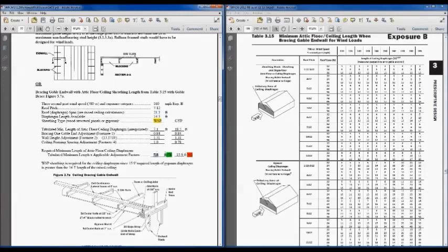That means that you have to sheathe that vaulted ceiling with wood structural panels if you're going to use that to block that end wall on the structure. And then, in addition to that, see this figure here, 3.7a, you're going to have to make sure you've got sufficient blocking into that system to keep a hinge from forming there where you are framing up to that height.